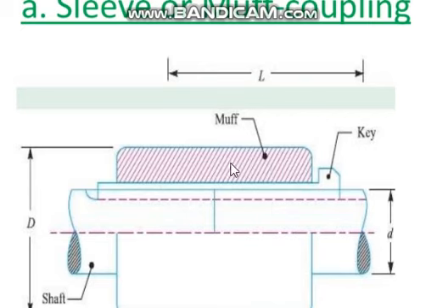This is shown in half section. Here the shaft is shown broken. Actually, in machine design, the break should be drawn in an S-like shape. Here hatching is on this side, which means the other side hatching should be on the other side. Nowadays proofreading is not done properly, that's why these mistakes come. If it is this side, the hatching should be on the other side. That is how we do machine drawing.